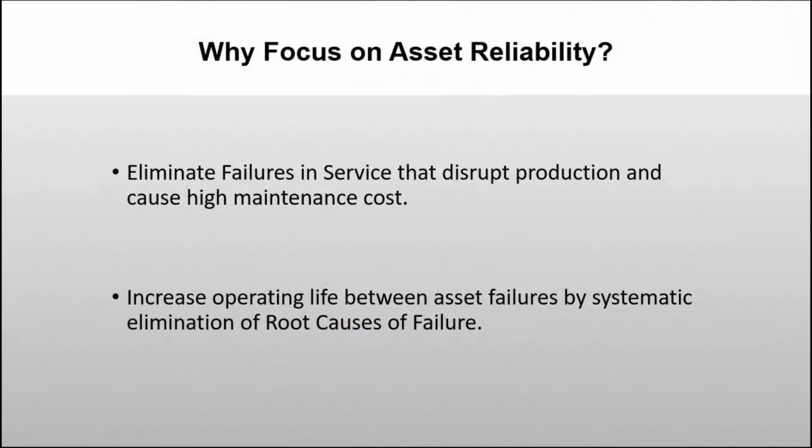And a longer term area is increasing operating life of those assets by understanding where we have repetitive failure modes and taking on processes to systematically eliminate those root causes of failure. This best practice we're talking about today, centralizing your management of your condition monitoring tasks, really is more associated with this first goal, eliminating failures in service.